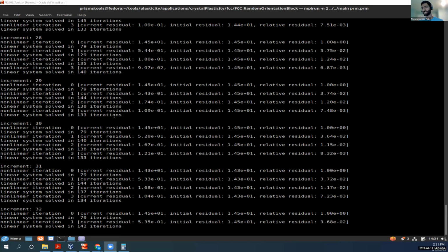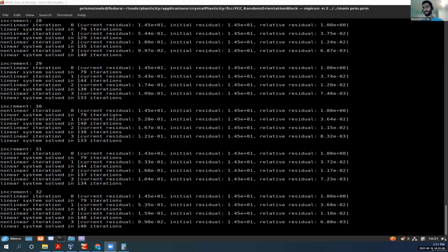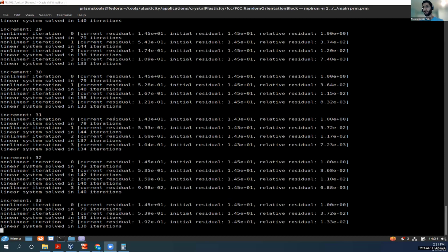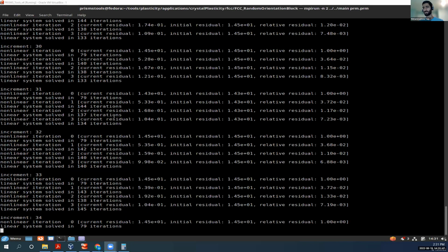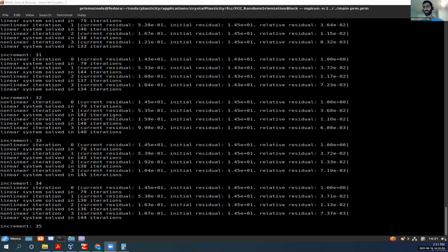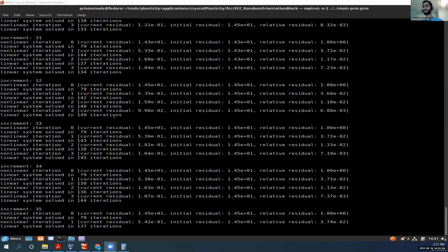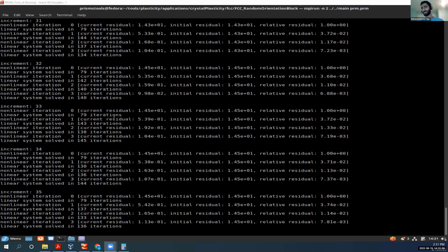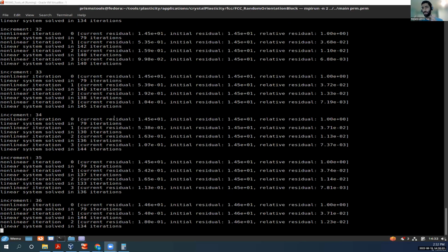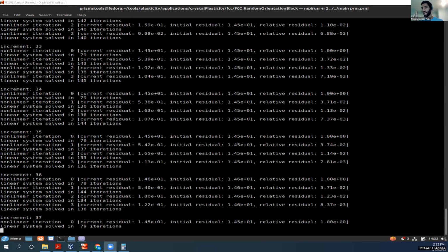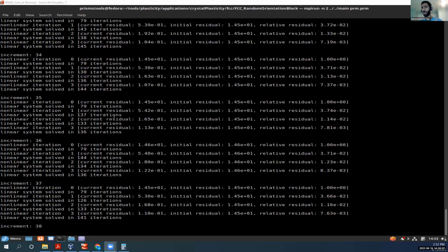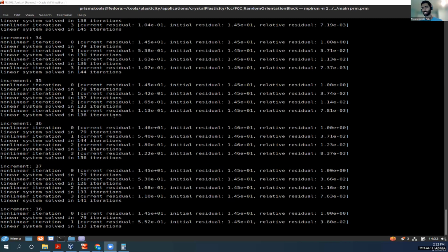But the best way to figure out what the problem actually is, when you are doing make release, do make debug. Just to give you an idea, last week I was doing an installation on our new cluster, and everything looked good. But when I was running the simulation, I got an error after the first increment. When I did make debug, it showed me the line where LAPACK was used, so something was wrong. Then I figured out the LAPACK installation was not working.